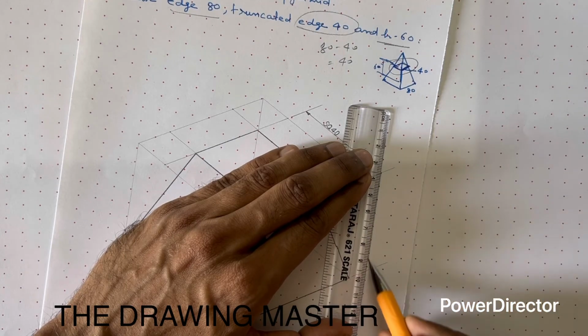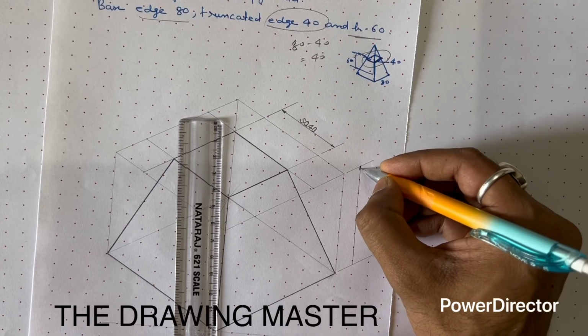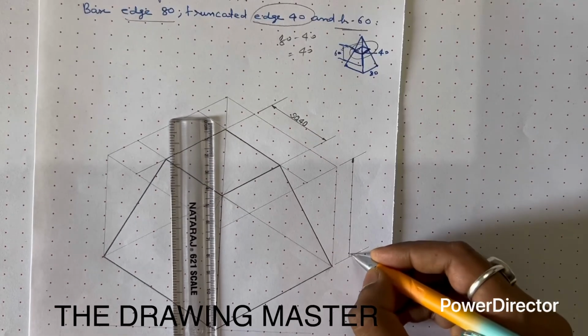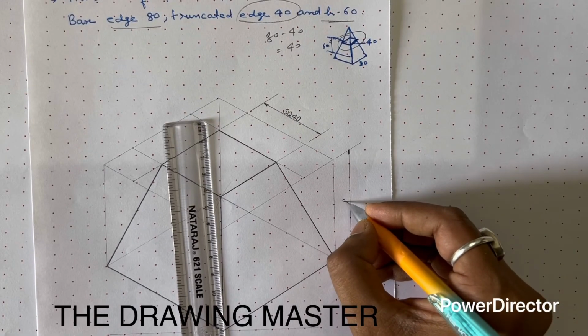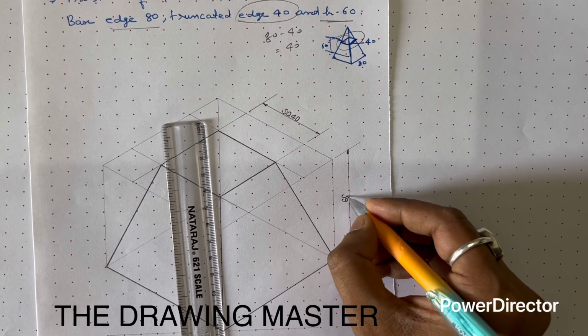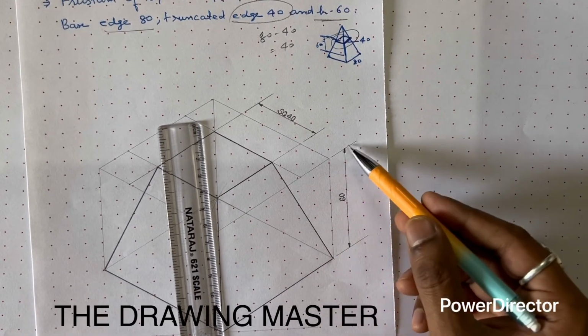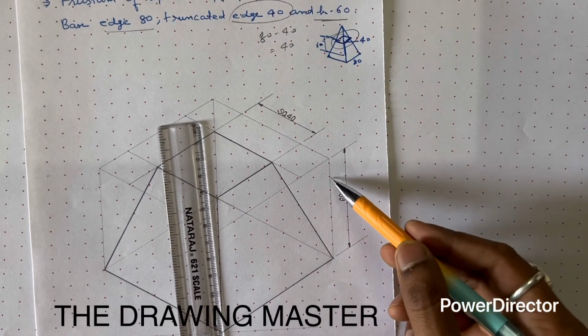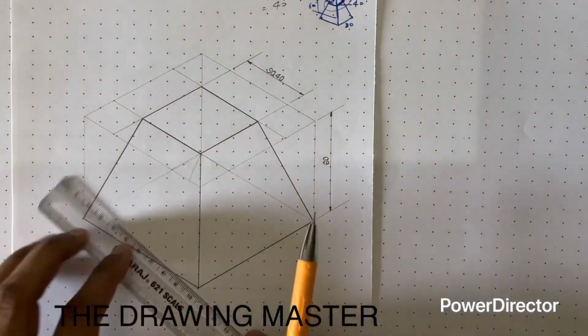Now the dimension line is a vertical line. Now this is the height of 60. You can see extension lines are always at 30-degree, and the dimension line is parallel to the object. It will always look like a parallelogram.